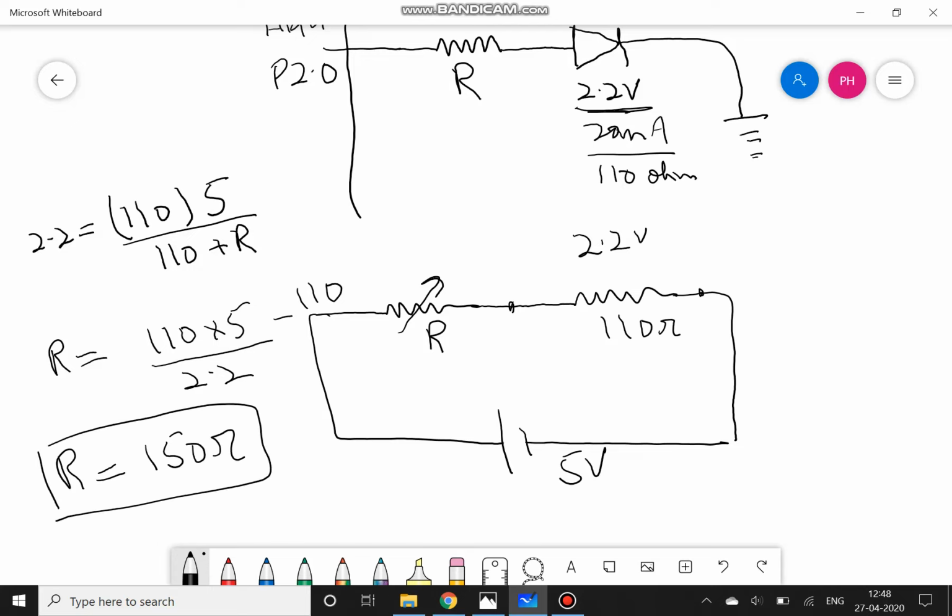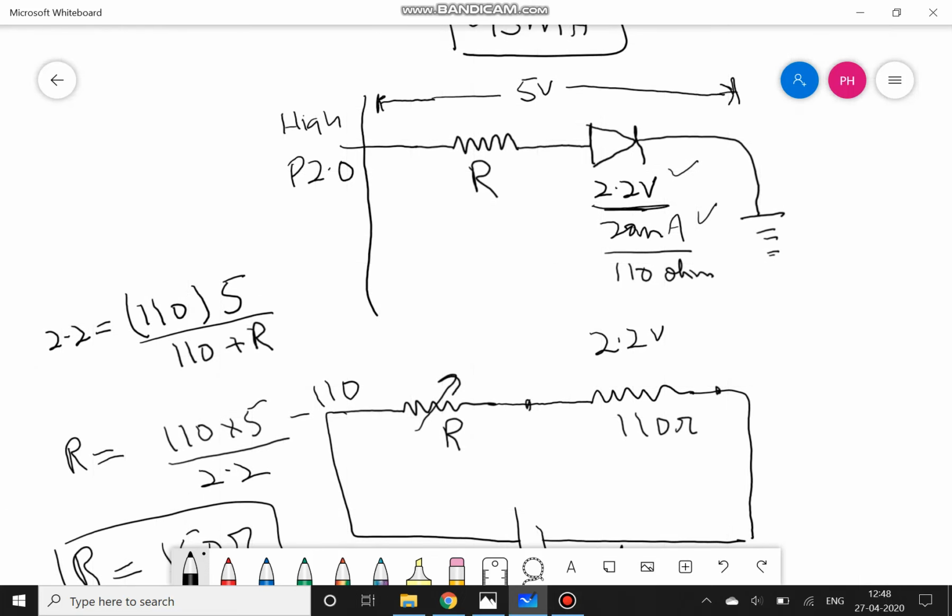So to connect a green LED of 3 mm diameter with 2.2 volts of operating voltage and maximum forward current of 20 milliamperes, I have to use a current limiting resistor of approximately 150 ohms. That will limit the amount of current that flows through the LED.